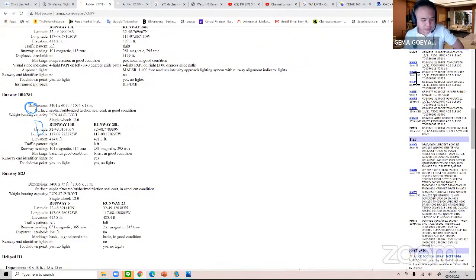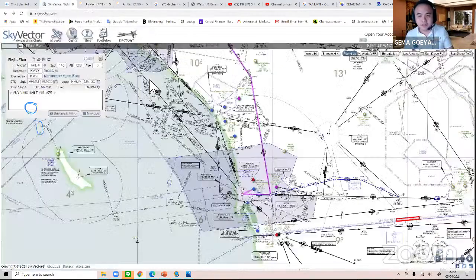Right. Okay, so when you fly instrument, the best way to decide when you want to put in the alternate is to remember the 1, 2, 3 rule. Part 91 is a little bit different from Part 135 or 121. Part 91 is 1 hour before and after your arrival, your ETA. Then the ceiling and the visibility really matter. So you have to have at least a 2,000 foot ceiling and visibility of more than 3 miles. On the other hand, if the airport has no instrument approach procedures, then you definitely have to file an alternate. That's for your flight planning.